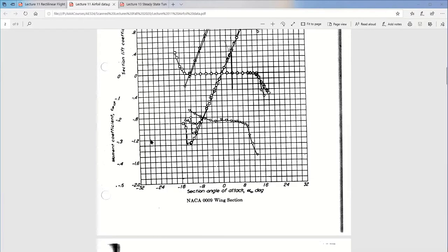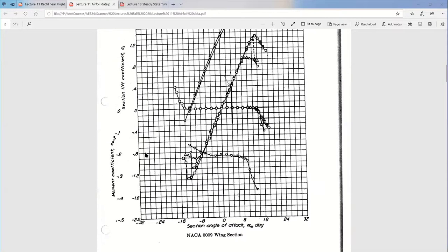And the key thing to notice, well, one of the key things, is that the axis number labels here are for lift, and these numbers here are for the pitching moment. It's real tempting and easy to read off a pitching moment value and come over here and read minus 0.85, but you have to look at the numbers in this column here instead. So this is lift versus angle of attack. This is pitching moment.